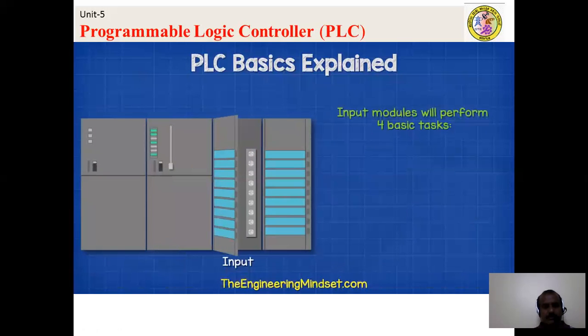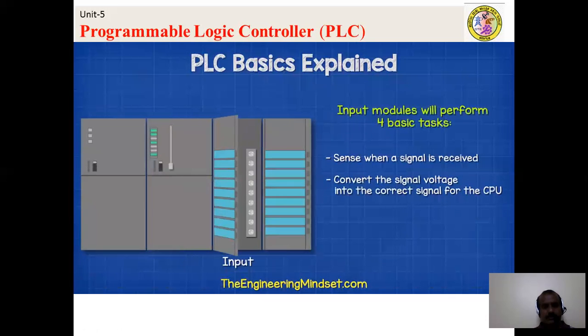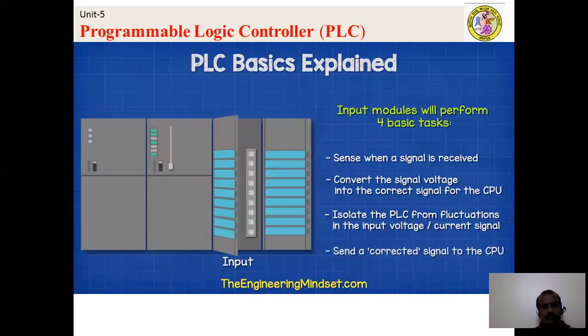Input modules will perform 4 main tasks. They sense when a signal is received, they convert the signal voltage into the correct signal for the CPU, they isolate the PLC from fluctuations in the input voltage or current signal, and they send the corrected signal to the CPU.